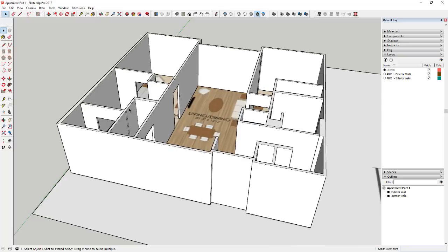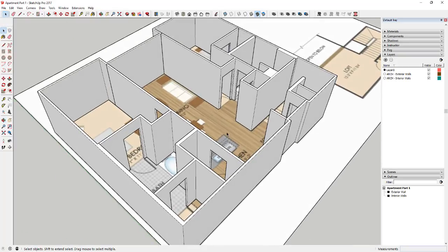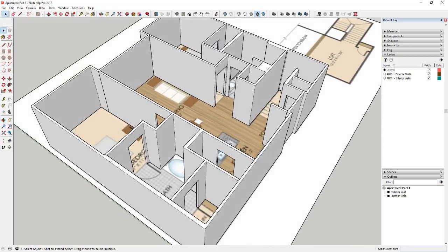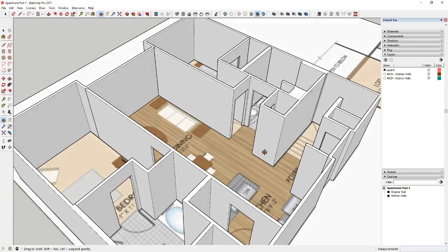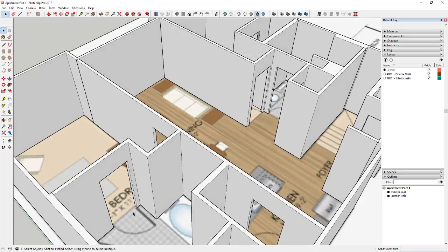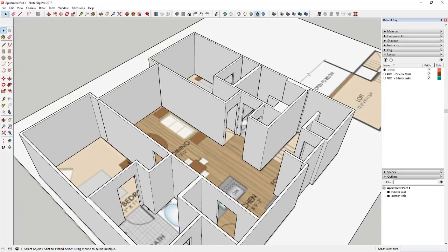And so the way that we're going to do that is it's important that you group this properly, because when we bring this into layout, sometimes you're going to want to create different line weights for your different openings. And so we need to make sure we model out our swings properly, and that we get our doors modeled as well.